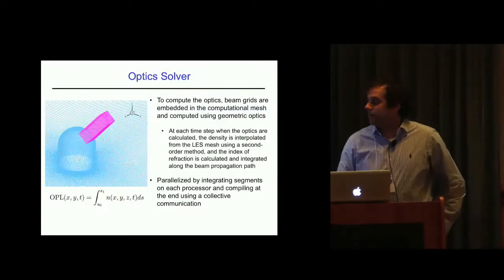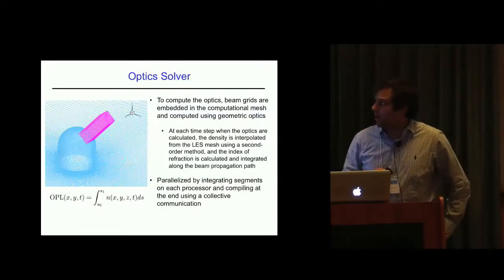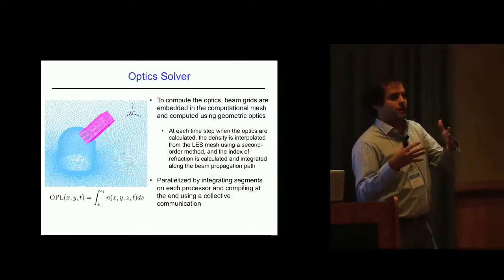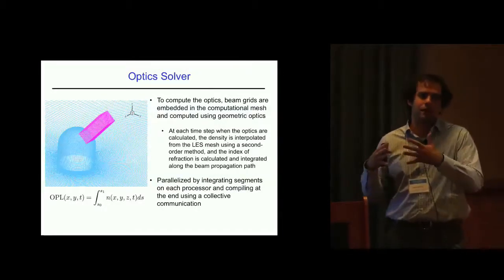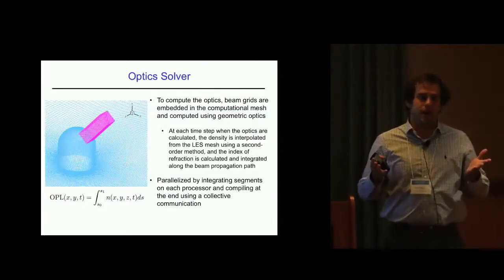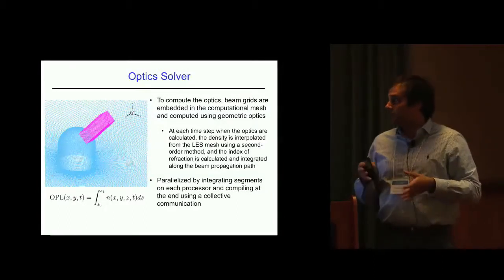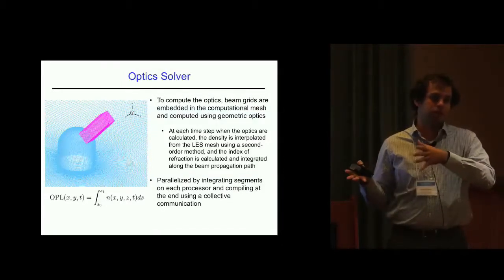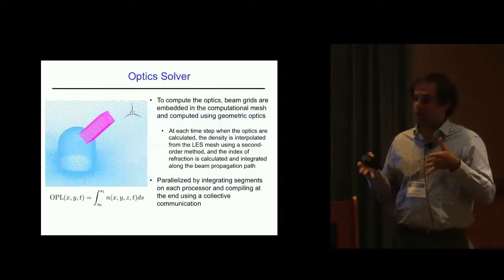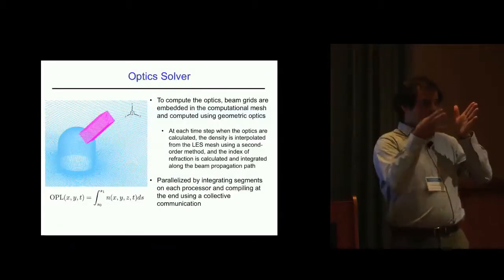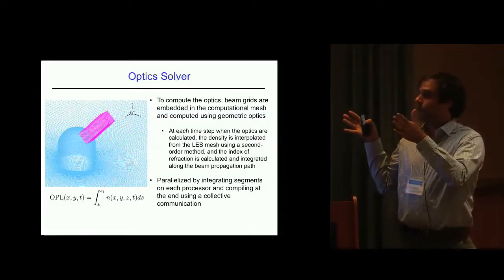So getting on to the core of this problem is looking at the optics. Like I said, these index of refraction fluctuations are really weak, so we don't really have a lot of scattering of the waves that propagate through. And you can use ray tracing to calculate the optical distortions. So at each beam angle that I look at, I have to embed a separate beam grid into my simulation. I'll show you in a second. I have about 400 different places I want to look to survey the entire optical environment of the turret.